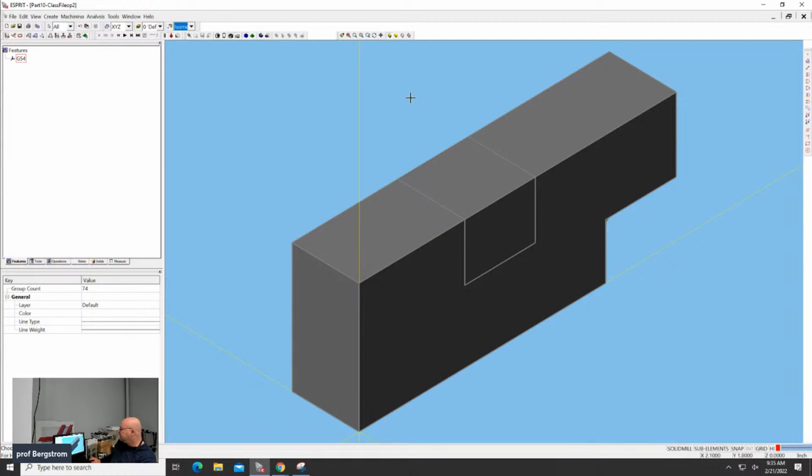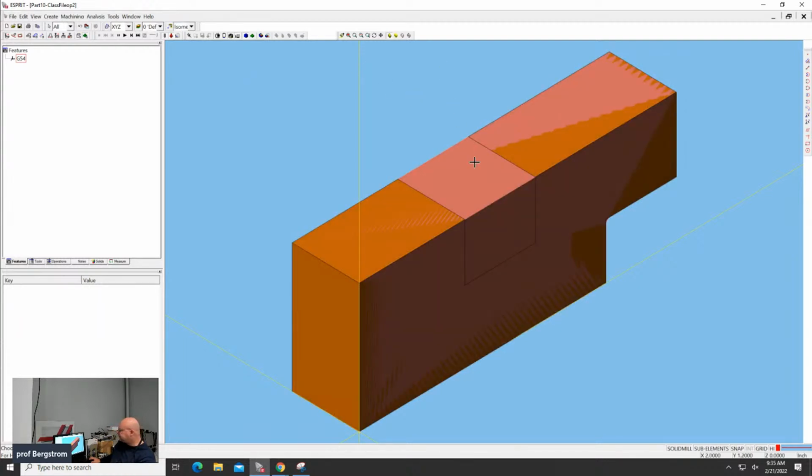All right. So we're in this orientation. You want to remove this material here. The part's already exactly the right size, so you don't need to do any facing or contouring around the outside. So to remove this material here, probably what I want to do is make an open pocket. So to do that, I'm going to go to the Create Features toolbar again. And it's so easy to create a manual chain to 4 different points. So I'm going to just hit the manual chain.